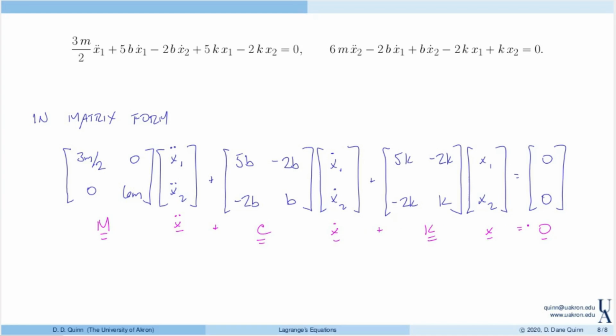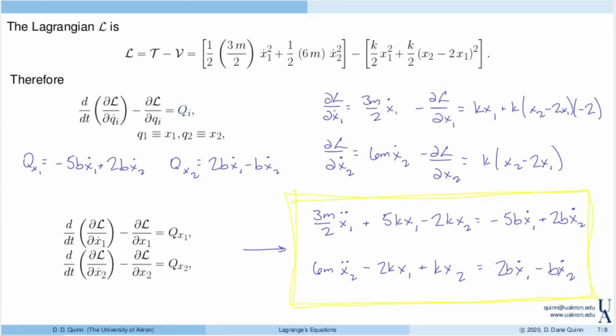So that's it. That's a nice modeling example dealing with disks that rotate, some relative motion between the two. I do want to point out that you may notice that the damping and the stiffness matrix look very similar. In particular, just take K here and replace it by B, and you get the damping matrix. So, in general, that's not true. It is true in this specific example.